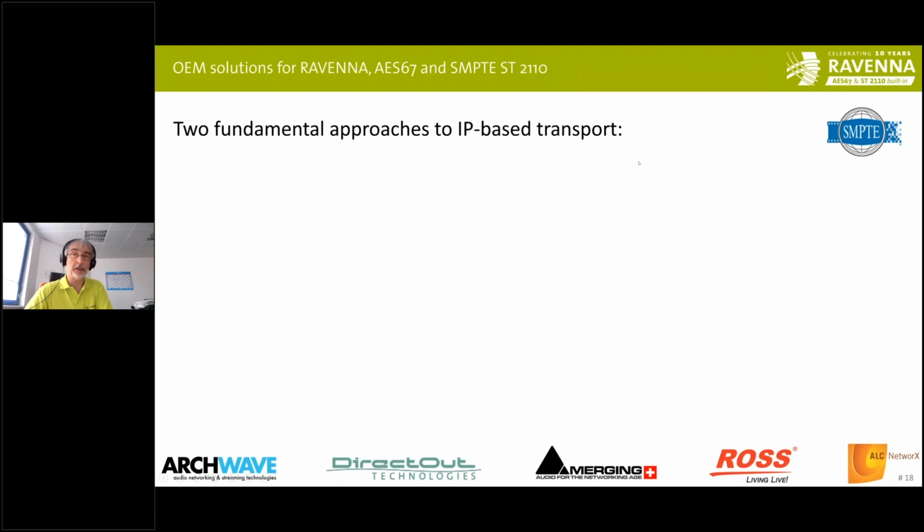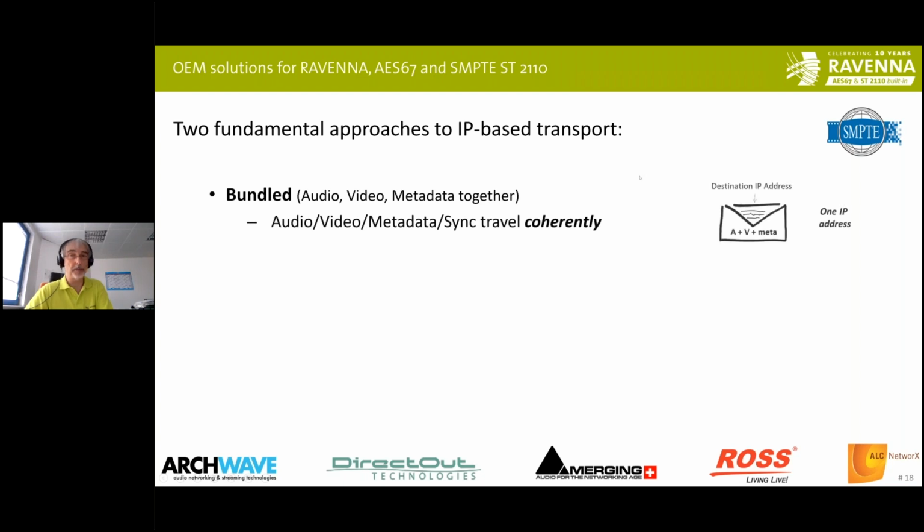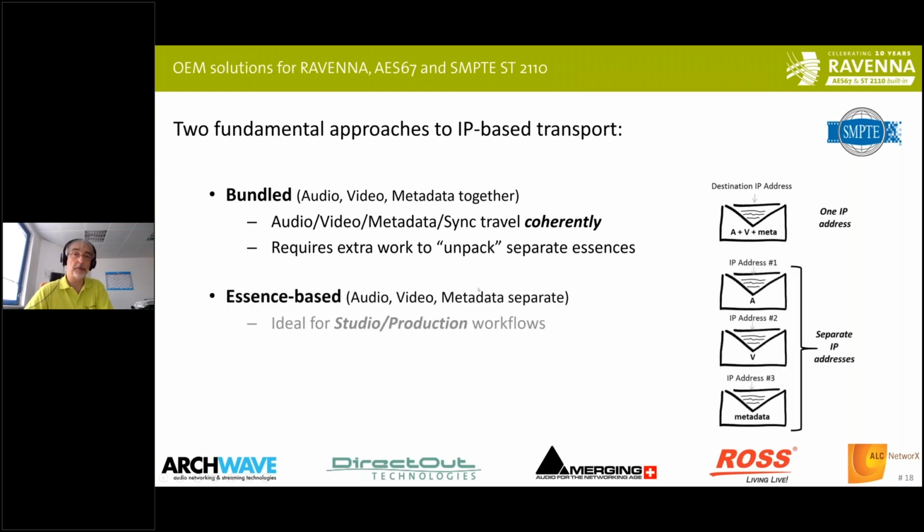So just in order to illustrate the difference between the already existing bundled approach, where we have an SDI signal in one stream, audio, video, and metadata, traveling in one IP stream, versus SMPTE 2110, which is the essence-based approach, where all the individual essences, audio and video and metadata, travel as independent, separate essence streams on the network.